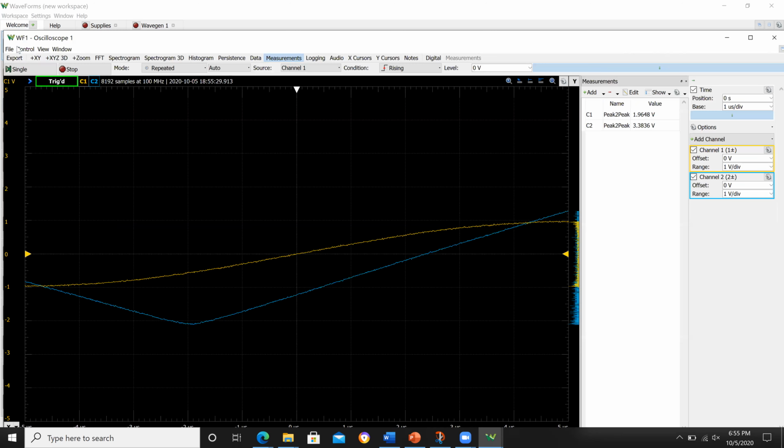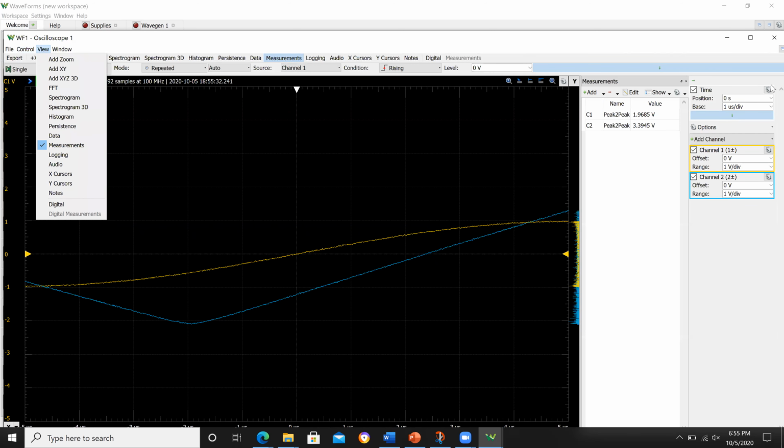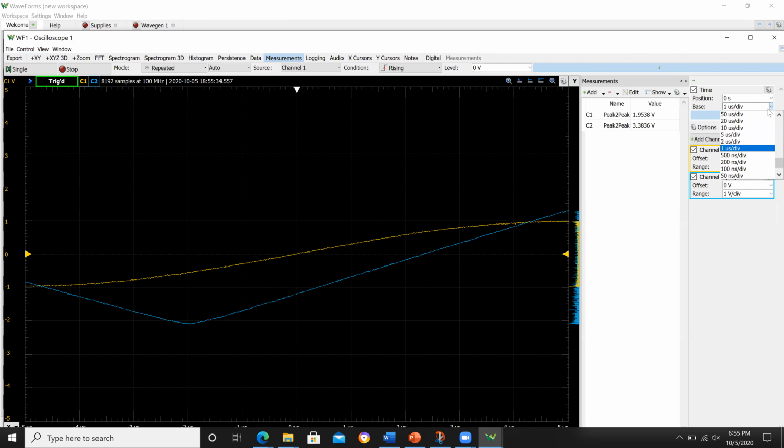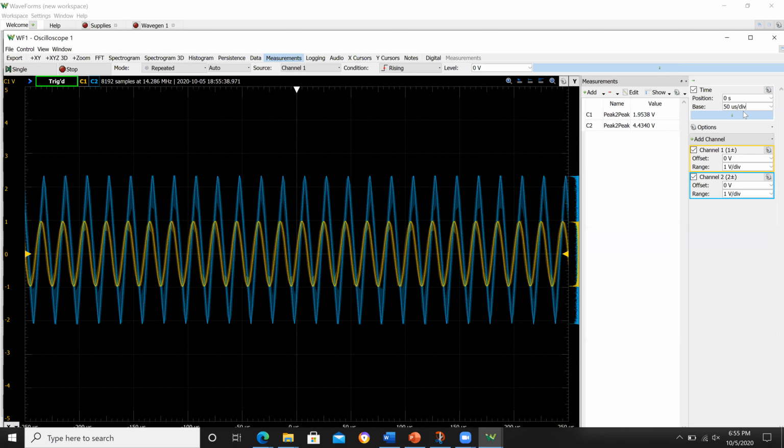And we'll go back to the scope. And let's see here. There we go. Okay. So now we're starting to get a little closer back to where the op amp can operate, right? And I think this is a better representation of slew rate for you. So the input still looks great, but the output looks horrible, right? You have a sinusoid going in, and you have a triangle wave coming out.